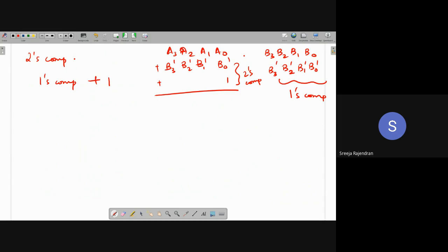So here I have converted the process of subtraction to addition. That means I already have an adder unit which I can use for subtraction also. I am eliminating the need for an additional hardware unit for standalone subtraction. So I can have a unit which is an adder, which depending on the need, whether I have to add or subtract, I can convert to do the process.